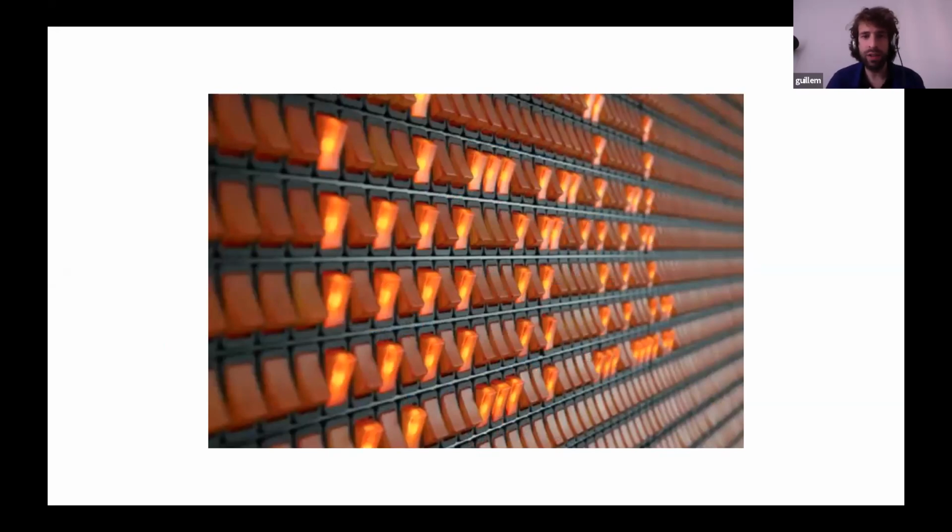So this will be the main introduction to bootloaders and flashing. You see, at the end, what we are doing is that inside our microcontrollers we have a memory that stores ones and zeros, which we could imagine as switches that could be yes or no, on or off. Then we create code with C or any other programming language that we compile, and once it's in our computer describing how the switches need to be turned on or off, we need a way to actually move those switches inside our microcontroller. Our microcontrollers don't have a switch panel where we could switch on and off and do all the combinations, and it would also be super slow. What we have is a way to take this file describing which switches are on and off, and flash it inside our microcontroller. So it's a convenient way of transferring these instructions from our computer to our microcontroller through a bootloader. That will be the end of the game in a way, because that's how we'll program all sorts of microcontrollers and processors.